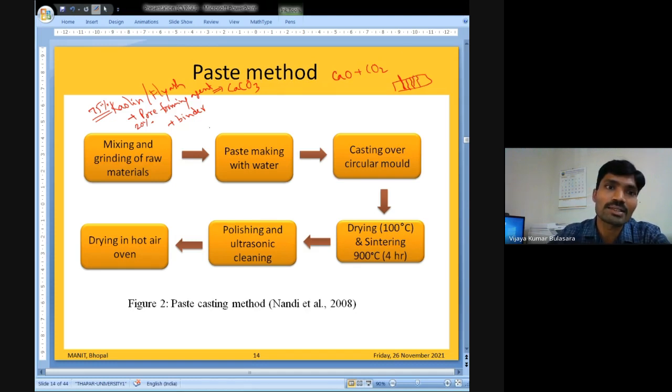Okay, and binders like sodium metasilicate are used for making ceramic membranes because it forms silicate bonds among the raw material particles of kaolin or of fly ash. Okay, so then we need to grind these materials. If grinding is fine enough, then we'll get uniform pores, because different particles of kaolin or fly ash will have different sizes. Okay, the size can range between 1 to 5 micrometers for the main raw materials. So fine grinding is useful in obtaining fine pore size of the membranes.